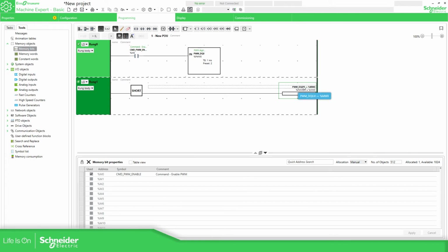I use the name of the instance that you can see over here, or you can use the address %PWM0.R. It's the same. Here you can use something to set the value, or you can use an analog input and then make some kind of scaling to limit this value to 0 to 100. That's going to be the duty cycle. So this one will be the duty cycle.